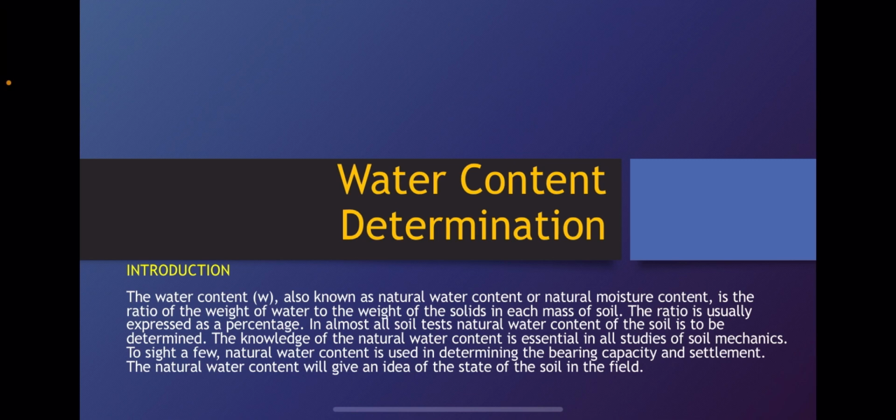moisture content, is the ratio of the weight of the water to the weight of the solid in each mass of soil. The ratio is usually expressed as a percentage. In almost all soil tests, natural water content for the soil is to be determined. Knowledge of the natural water content is essential in all studies of soil mechanics.